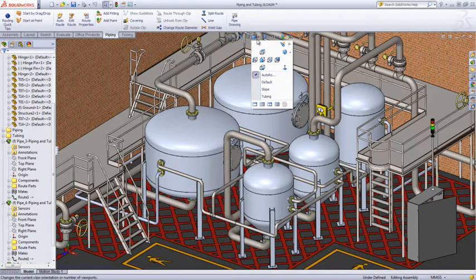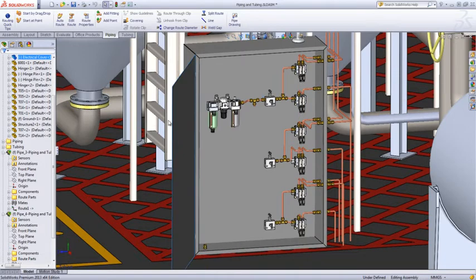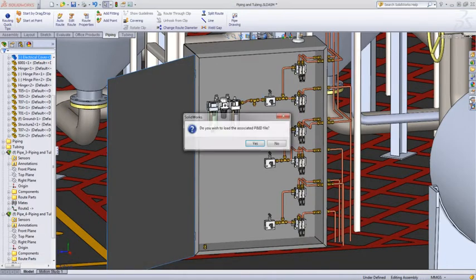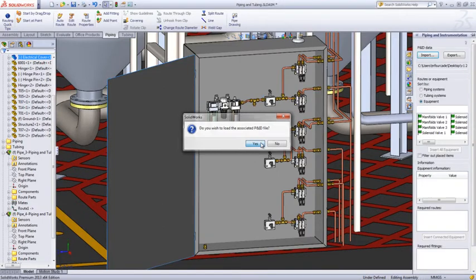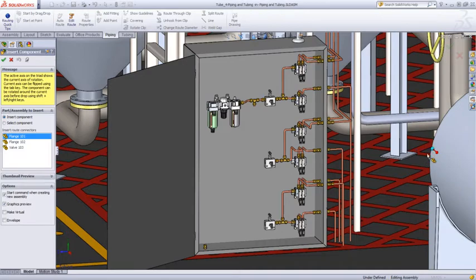Intricate hydraulic or pneumatic tubing systems can also be designed with SolidWorks. However, depending on the complexity and the scope of the project, it can be hard and time-consuming. That's why, to really help out system designers, SolidWorks 2013 now supports P&ID data for tubing. The tubing systems to process are listed along with the usual list of equipment and piping systems.